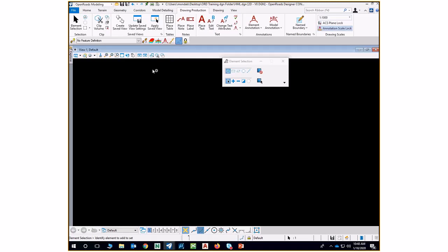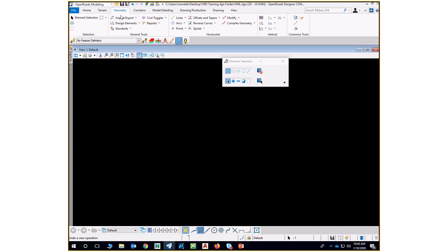So what I was telling, for designing a fresh alignment, you can go to Geometry, and first you have to set up the feature definition. To do that, you have to go to the Standard and Feature Definition toolbar. If you click it here, the feature definition toolbar will come. I've already docked it in here, and you can dock it anywhere on your screen.